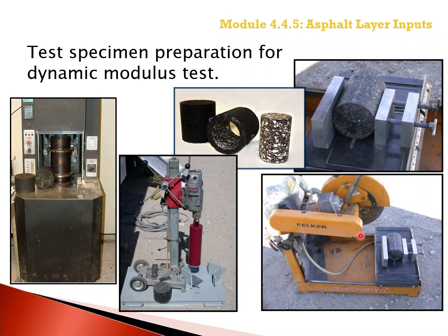There are other small scale specimens not shown on the slide that are also applicable for the dynamic modulus test. The reason for sawing the test specimens from the interior of a gyratory compacted sample is to achieve uniform air void distribution and/or uniform density throughout the sample. Previous studies have shown that the gyratory compactor produces specimens with unequal air void distributions throughout the specimens.